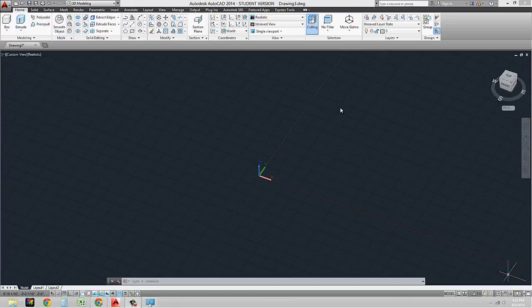drawing information underneath. So for example, if I'm using the extrude tool and I'm using a polyline that I had in my drawing, and I extrude it to a 3D object, it's going to lose the polyline, because basically it's taking that polyline and making it into a 3D object. So you don't get that polyline back. Now it's part of the 3D object, and you start to lose information. So I always say, save a copy and work with a copy of the file.